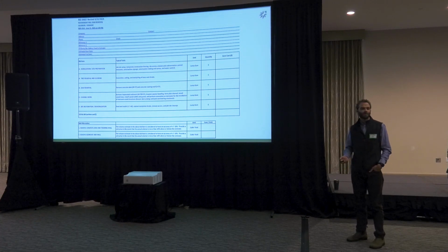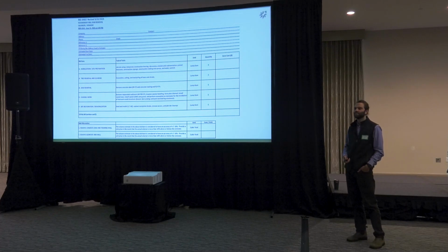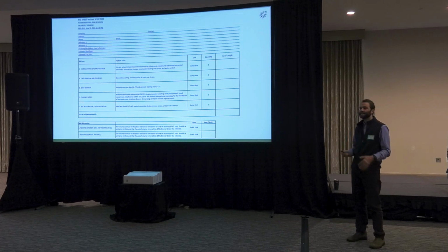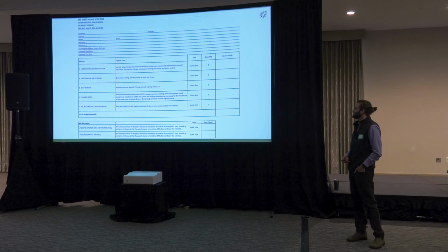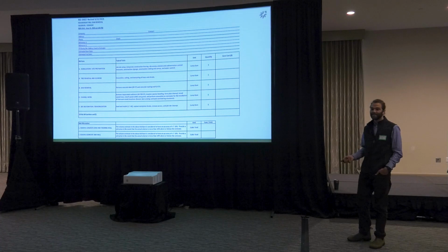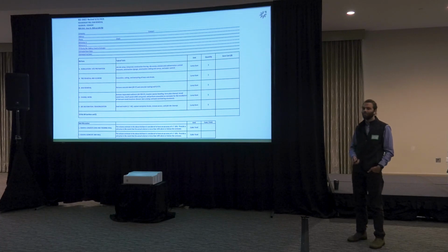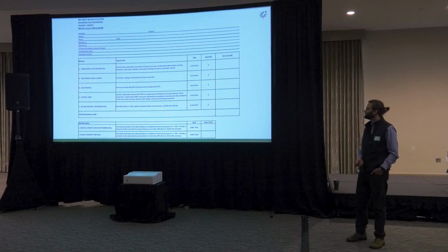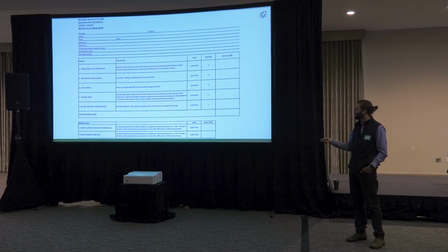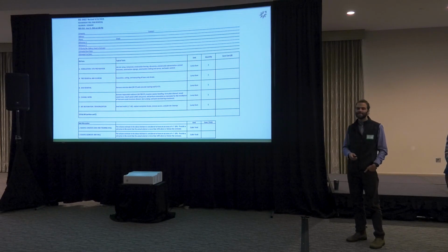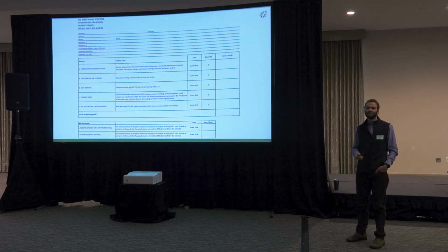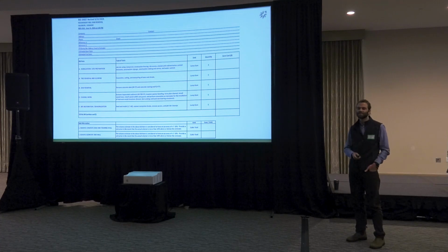As part of our design and our field work, we are calculating the volume of the dam that's to be removed, the sediment to be removed, and hopefully that ends up being about what is actually there and what is actually removed during the project. But we will typically include this add alternate so that if it's greater or less than 10%, which we often use, then there will be some adjustment to compensation for the contractor.